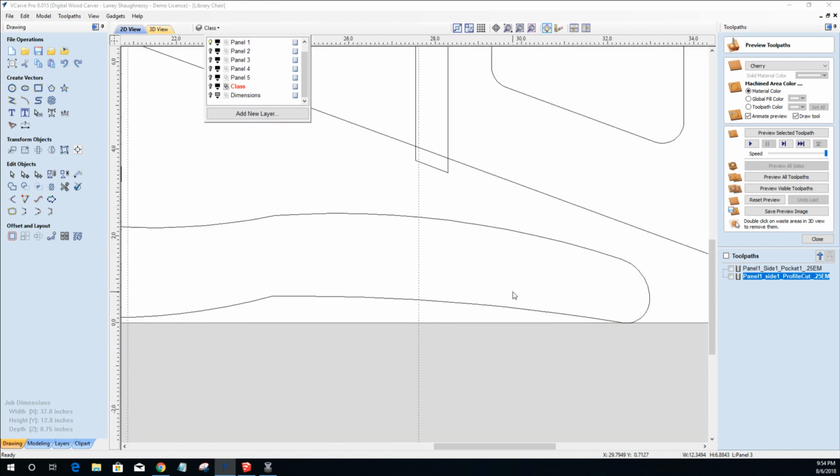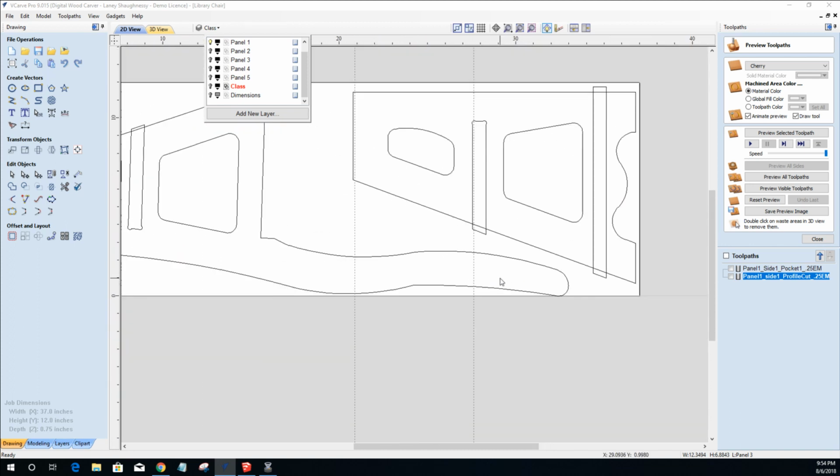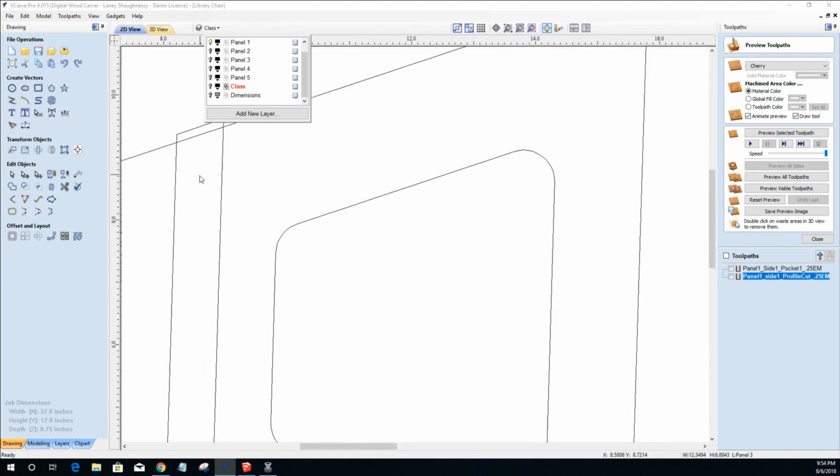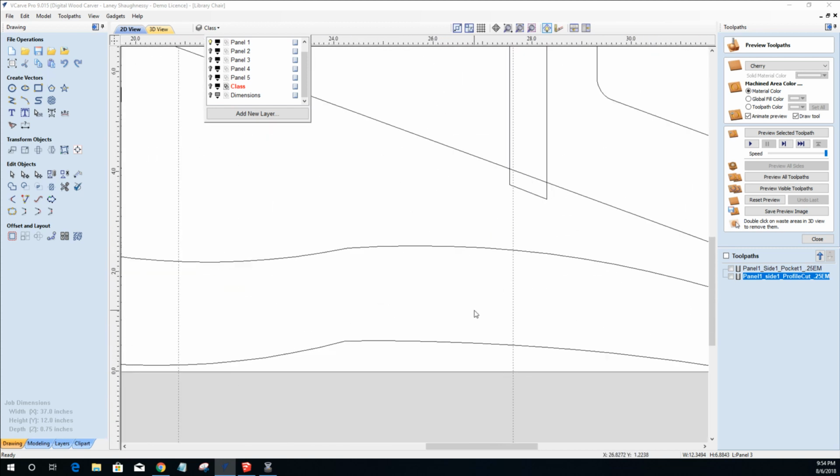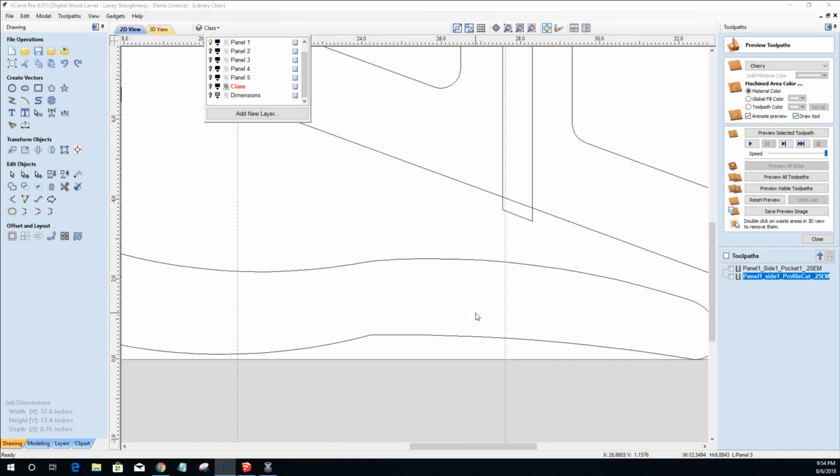On the chair backs, where the chair back is going to go, you can go ahead and have your CNC pre-drill the 2 holes here. And even have it pre-drill the 2 holes here where you're going to drill into the shelf for reinforcement. And you can even have it countersink. You can use like a 1/8 inch or a 1/16 inch end mill for the pre-drilling of the hole, and then a 1/4 inch end mill for the countersink, and then as far as plugs, you can cut out some 1/4 inch dowel.